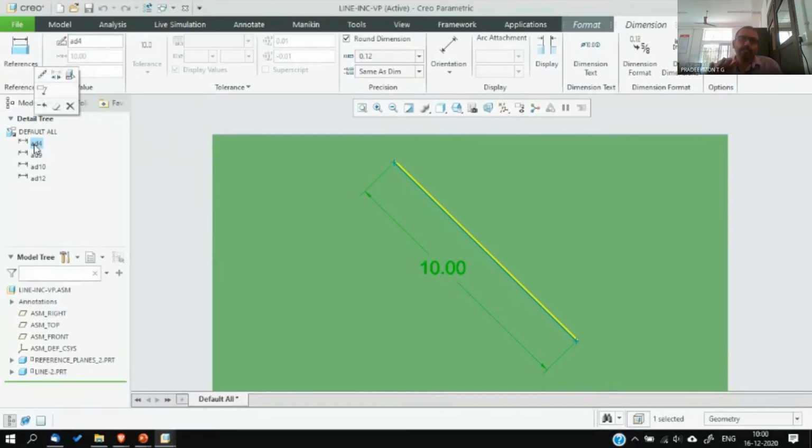So this condition you have to keep in mind, that is when the line is parallel to HP, in the top view you will be getting the true length as well as the true inclination with respect to VP, that is, the angle phi you will get.